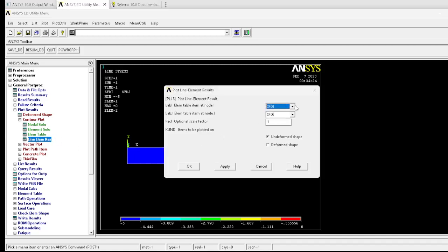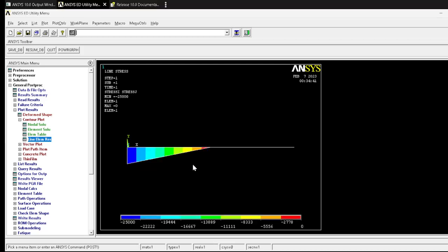Now to view the stress for I node, stress I, J node, stress J. So anyway, this also we got the maximum. So here the maximum will be there, that is minus 25,000. But it's showing minimum, right? Why? Because the blue column is in the negative direction, more than negative value it is minimum, but this is only the maximum. So this question they have not given, but in addition to this problem I just explained here itself, in the next upcoming problem also they are going to ask compulsorily, so in most cases shear force diagram as well as stresses.